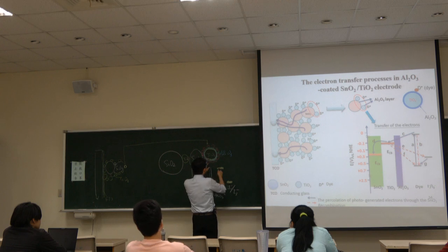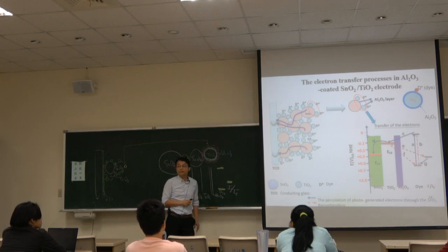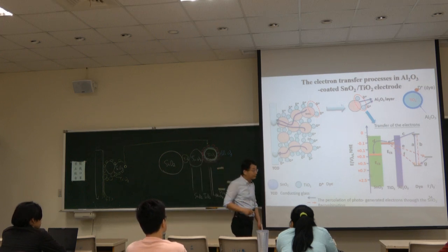So this is able to do. Okay, you can use some precursor of the aluminum oxide and using some stirring process, and inside you mix with the TiO2. So therefore, aluminum oxide could be formed very thinly on the surface of TiO2. It's possible. Okay, so this is able to achieve such phenomena. Okay, understand what I mean?